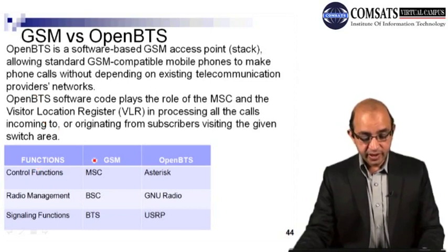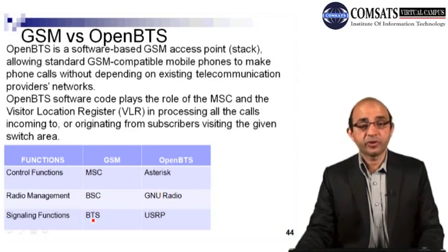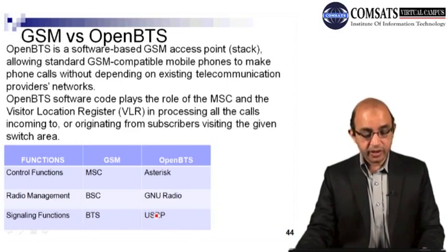So functions: here we have GSM, and here OpenBTS. MSC control functions are replaced by Asterisk. Radio management is performed by BSC, and here we have GNU Radio, and signaling functions are performed by BTS, and it is being performed by the USRP kit.